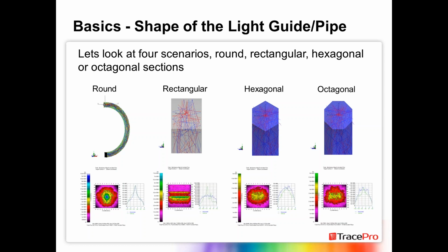And then you go off and do a photorealistic render at one of the 5 different settings: low, medium, high, up to extremely high. Now the second way is a luminance calculation / radiance, where there are 3 tabs at the bottom that say system, source, and model, source, and luminance. You go into that luminance tab, and then you specify the view that you want. You specify the number of pixels that you want to do the evaluation on, and then you go and do a ray trace, which will do both a reverse ray trace backward and a forward ray trace.